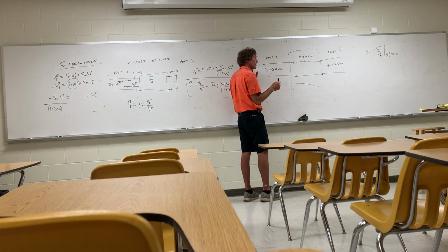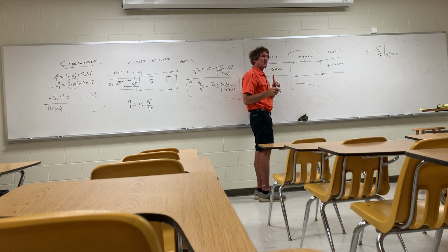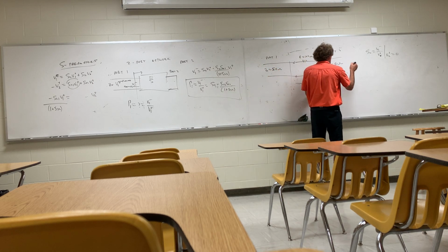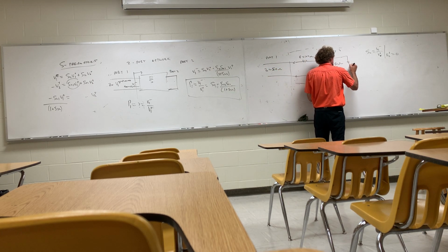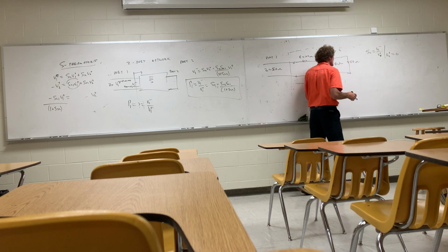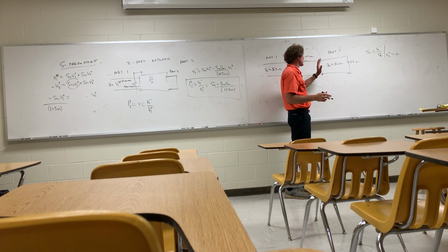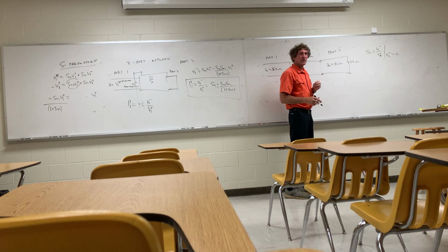So, the first thing I do in my mind, this is a little thought experiment. I'm going to terminate this thing to a 50 ohm load. And the reason I'm doing that, there will be no reflected waveform coming back into this port. So I know I can guarantee V2 plus is 0. You all follow me on that, class?